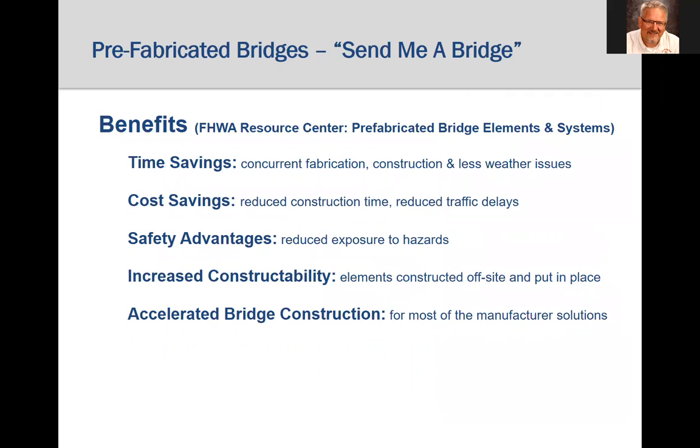In the context of Lecture 6, prefabricated bridges are structures that are designed and fabricated by manufacturing firms and delivered to the site ready for erection. Some people call them pre-engineered bridges, but that is not entirely true since each bridge is individually designed and fabricated for the particular site and load characteristics. Most of the examples we will look at and most of the prefabricated bridges from manufacturers are also applicable for accelerated bridge construction.